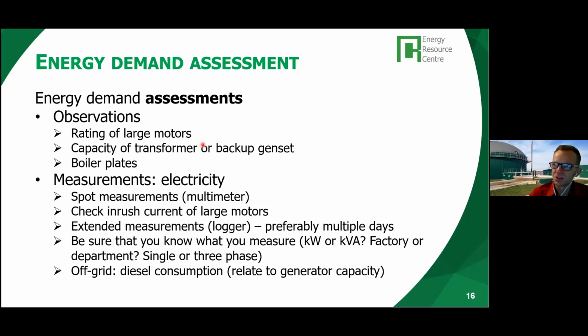If you have large motors and you don't have any soft starting equipment, for example, then you can have very high startup peaks of large motors, and that can, to a large extent, determine the maximum kVA of your factory.